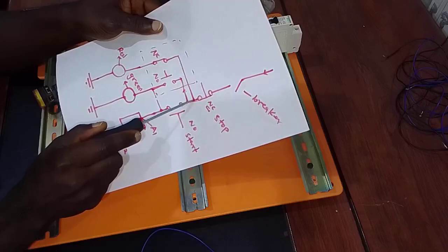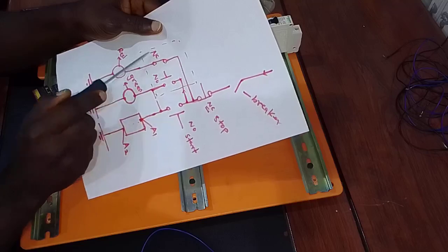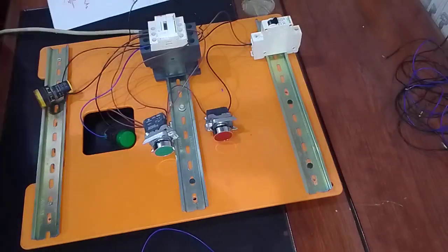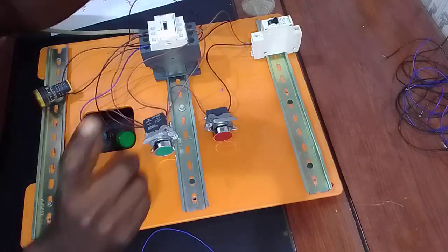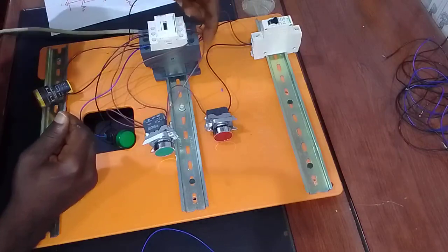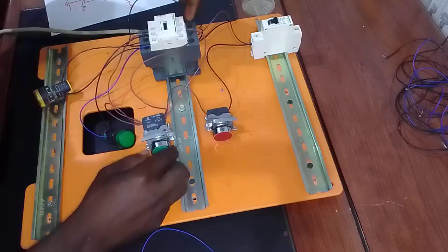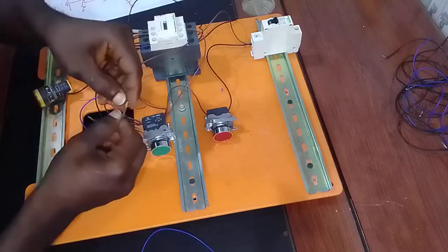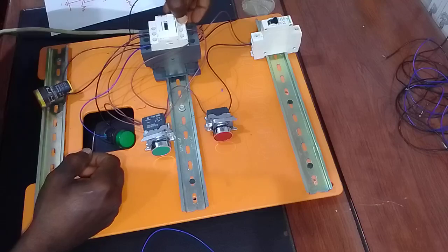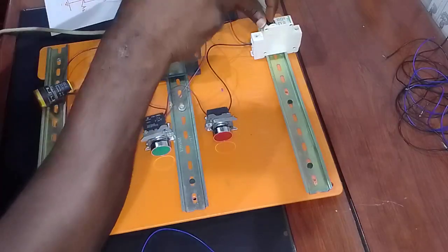So we are going to loop from one of the lifelines into the input of our normally closed contact. Now we get another conductor to loop. Already we know that from here we have a branch that goes to the start push button. So we're going to loop from that particular point, the input of the normally open contact.